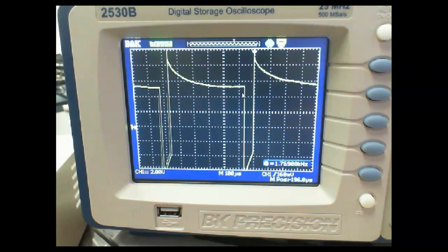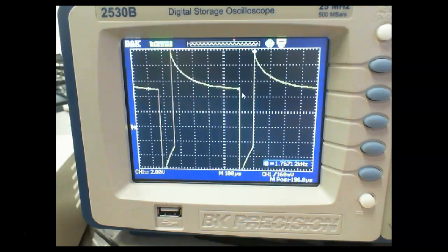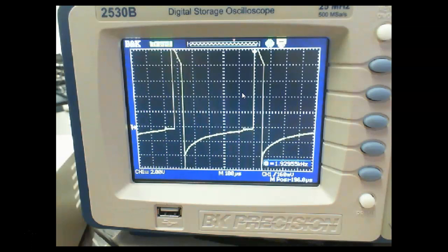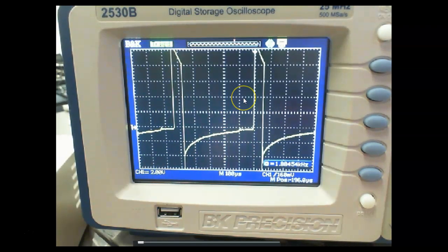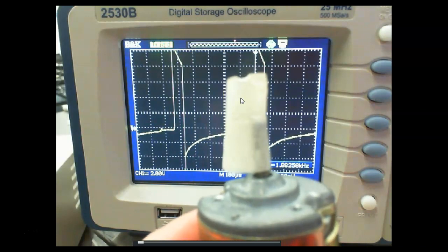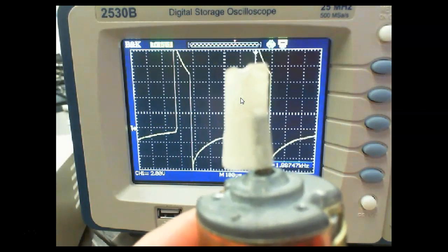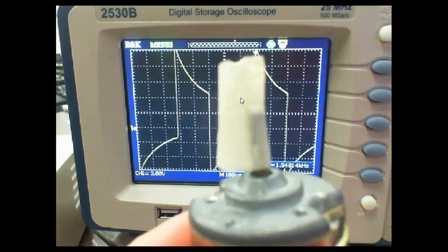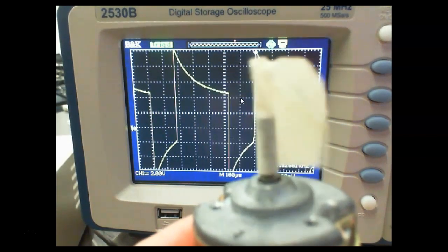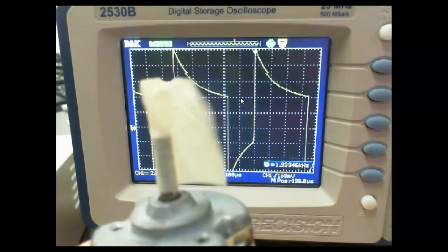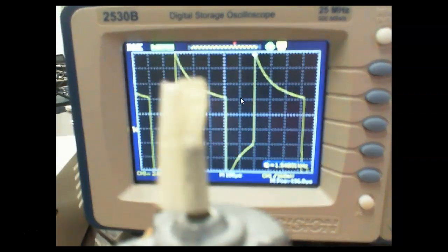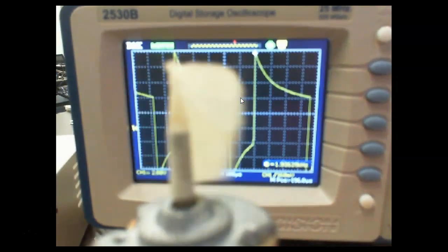Well, what I can do with this is change what we call the pulse width. Now, this is the actual motor. Right now it's stopped. I can't run it full speed. If I come over and make the pulses bigger, this is just a regular little DC motor. I know at home it looks kind of weird because of the sync rate of the pictures. But by changing the pulse width, I can precisely control the speed of this DC motor.